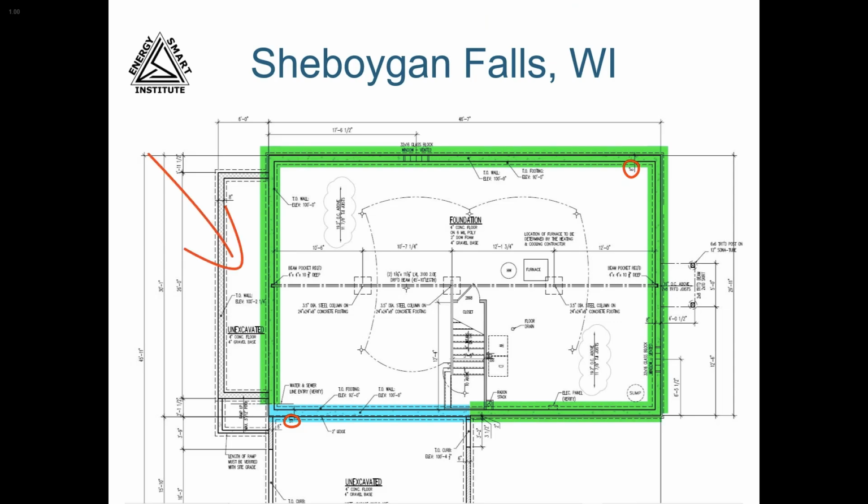There's another area of concrete against the foundation wall, but that's beneath a covered porch, so it's not an enclosed garage type area. It's open to the elements, so it's considered ambient. If this were instead an enclosed equipment room or something like that, then you'd treat it just like the garage, and that portion of foundation wall would be modeled separately as well.